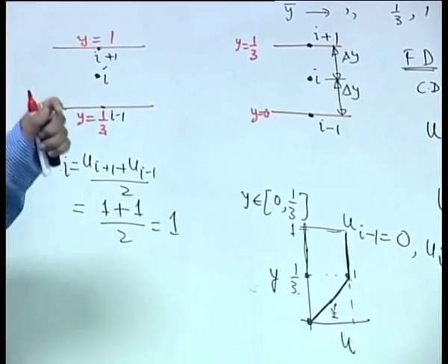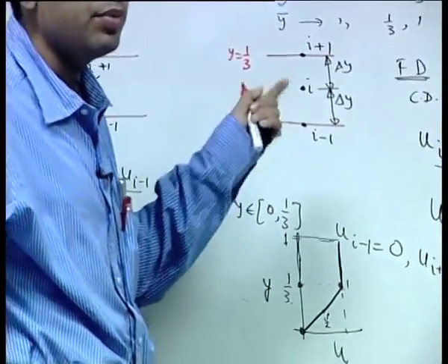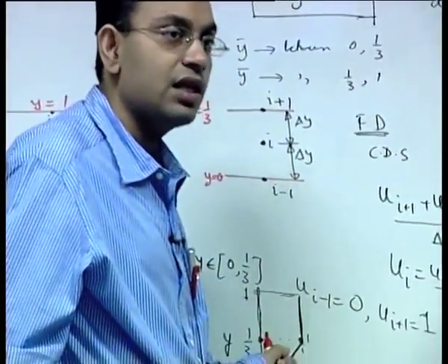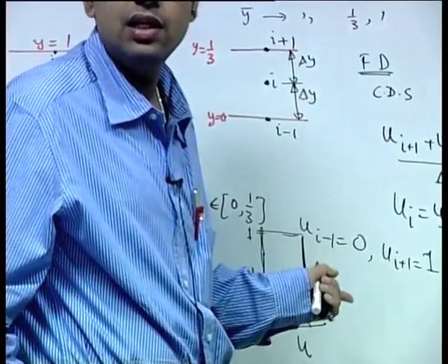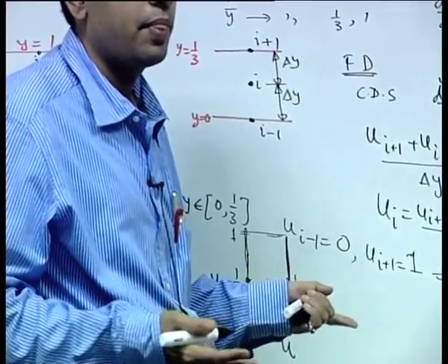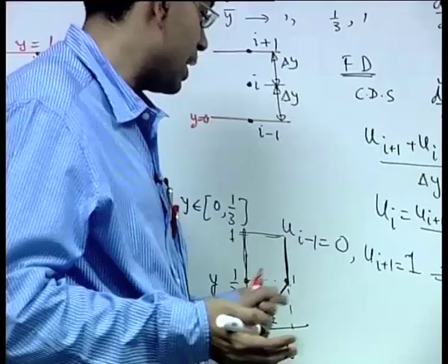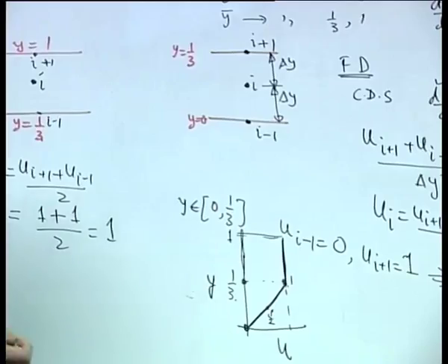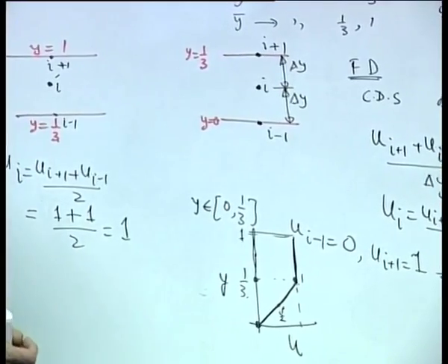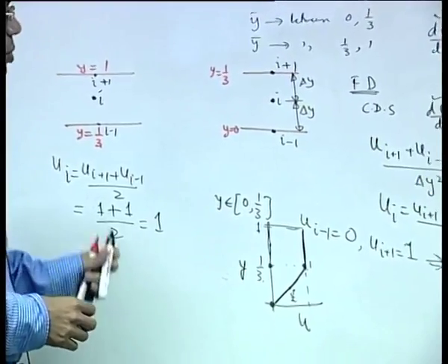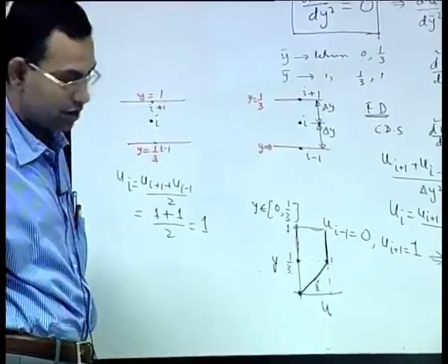Because the approximation of the Taylor series has been based on up to a linear term and the actual profile variations are linear, these actual solutions are linear. So, you get the exact solution and the numerical solution the same, because the exact solution also is a linear velocity profile. Then let us look into the corresponding problem with the finite volume method.